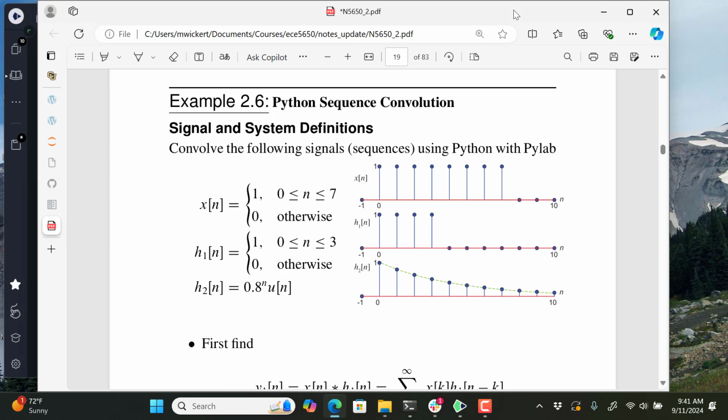If I flip it over and send it through a second time, the phase gets unwrapped, but the amplitude response gets applied twice. So that has some really nice properties that double the frequency response amplitude of a filter, and the phase distortion gets removed the second time.